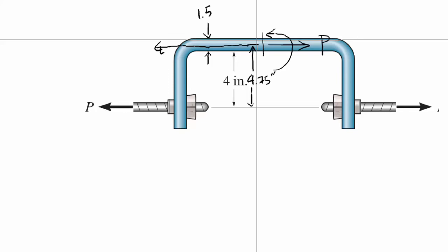So here again, you're given some hints, and you're being asked to solve for what the P load is. We know, different from the previous problem, which was problem 7-19, that in 7-19 they're saying that the stress would equal 0 because that is what you're solving for. Here they're saying that your allowable stress is equal to 30 ksi.